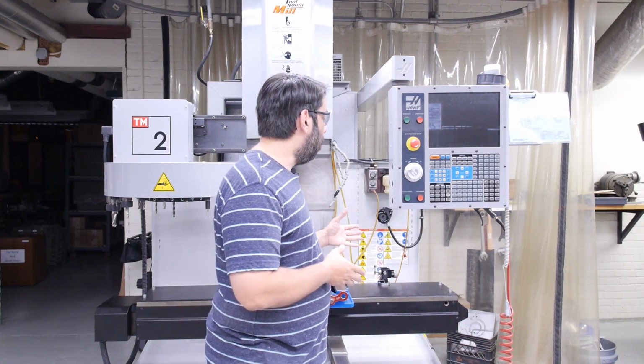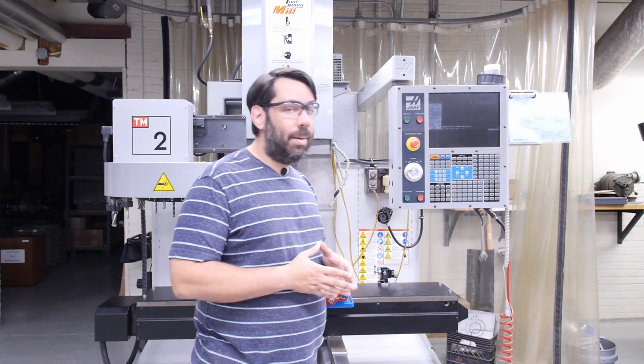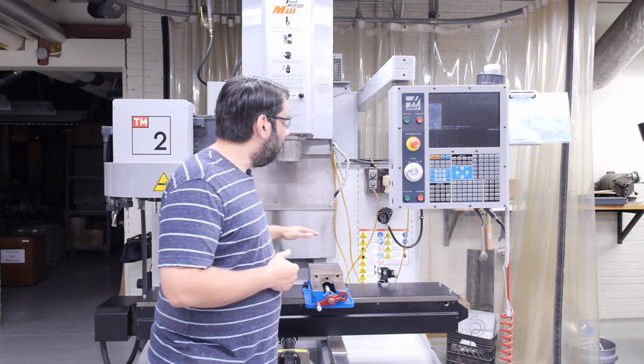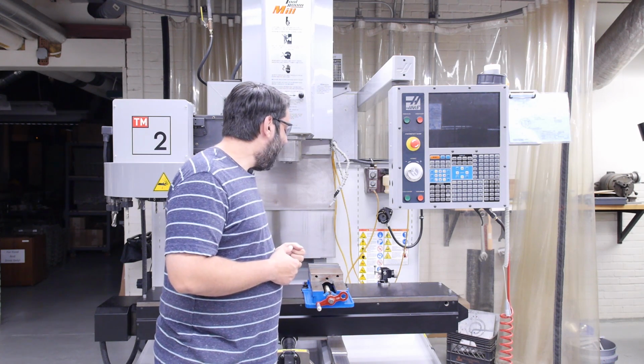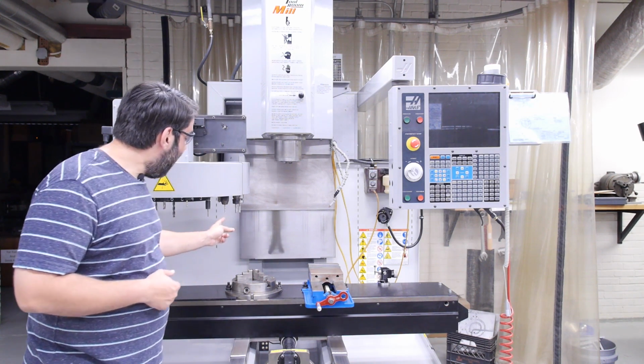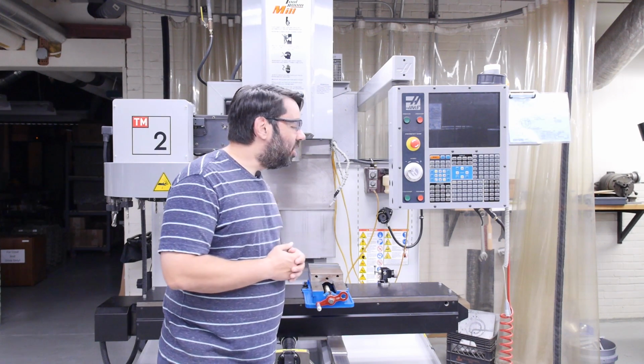Starting out, we ask them if they know what the acronym CNC stands for. Now usually, the students can come up with two of the three words, computer, controlled, and that's pretty good. Formally, we tell the students, computer numerical control refers to any machine tool, milling machine, lathe, bandsaw, etc., to which a computer system has been attached, which automates various motions and functions on the machine. Examples of this include axis motions, automatic tool changes, and the ability to automatically command any desired spindle speed.